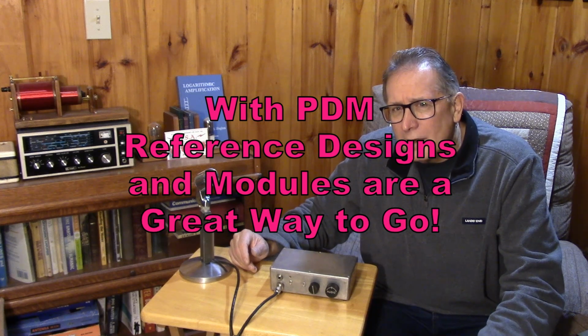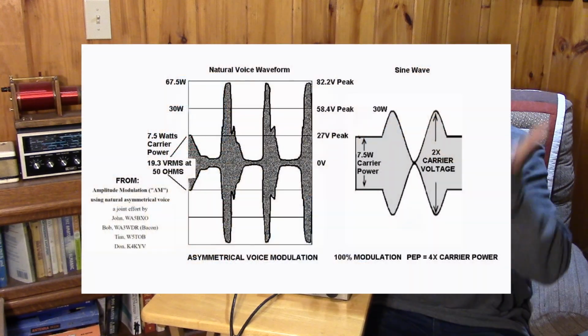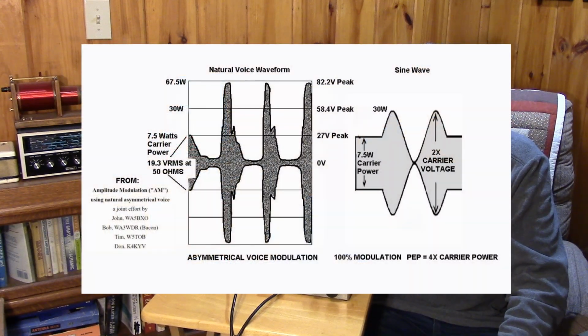So we take our first principles transmitter and we realize that we are not getting very good talk power. The RF power is very low, right? And let's see what we can do to try to pep it up a little bit. The first thing, and this has been suggested by many of the commenters and also by the community that I was trying to talk to that have been doing PDM for many, many years, you need to get more modulation density. You need to get more upward modulation.